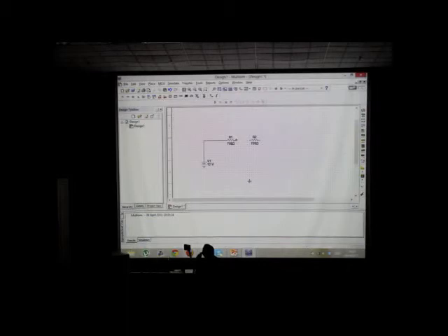In a similar way, you connect and you bring here. You connect this, you bring until here. You connect to ground, it's done. And this end you connect here, and I think it's connected. Okay, so basically this is our circuit and it's connected as we can see. Now we can run different kinds of analysis like DC analysis, AC analysis, and whatever we want. AC will not apply here because we have a DC source.